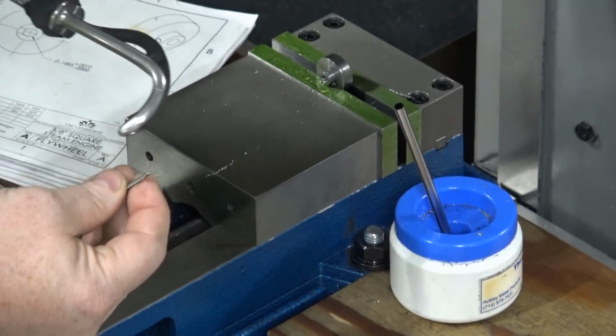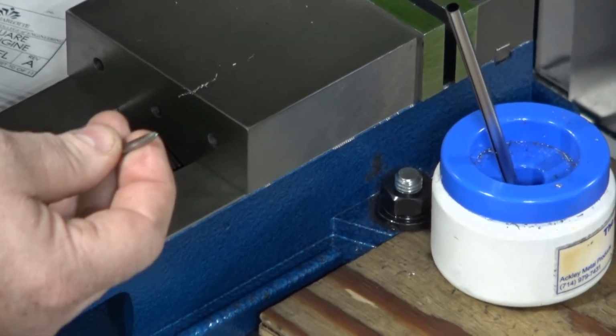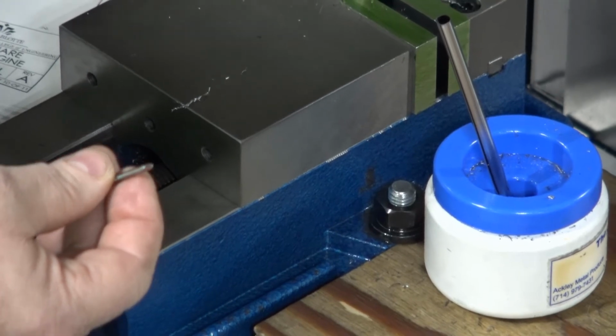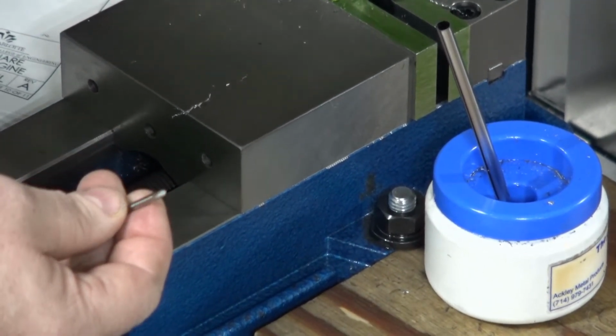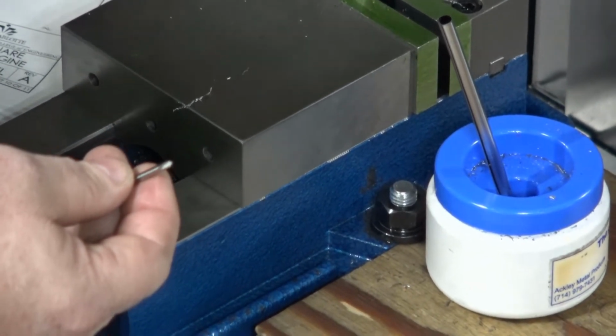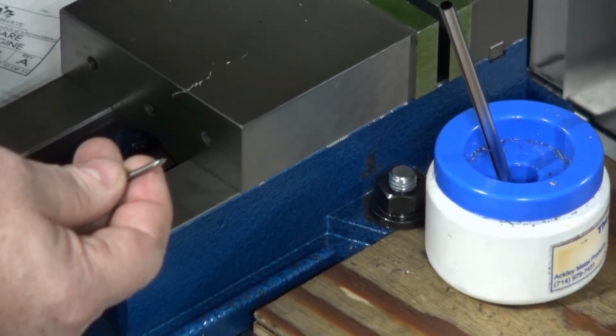Well, that front side cone, that little bit of a taper, kind of restricts my tap from going too terribly deep, because there are several threads that it takes in revolution for that tap to get up to the full thread form. Okay? We want to get the full thread form.